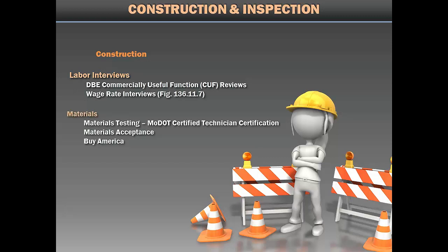So now let's talk a little bit about materials. Materials testing must be performed by a MoDOT certified tester and must be performed by an independent representative of the LPA and paid for by the LPA. The contractor cannot perform quality assurance testing or be responsible for paying for it. If your inspectors or testing lab need to become MoDOT certified, they should see the training section of our LPA website for information on how to get certified.